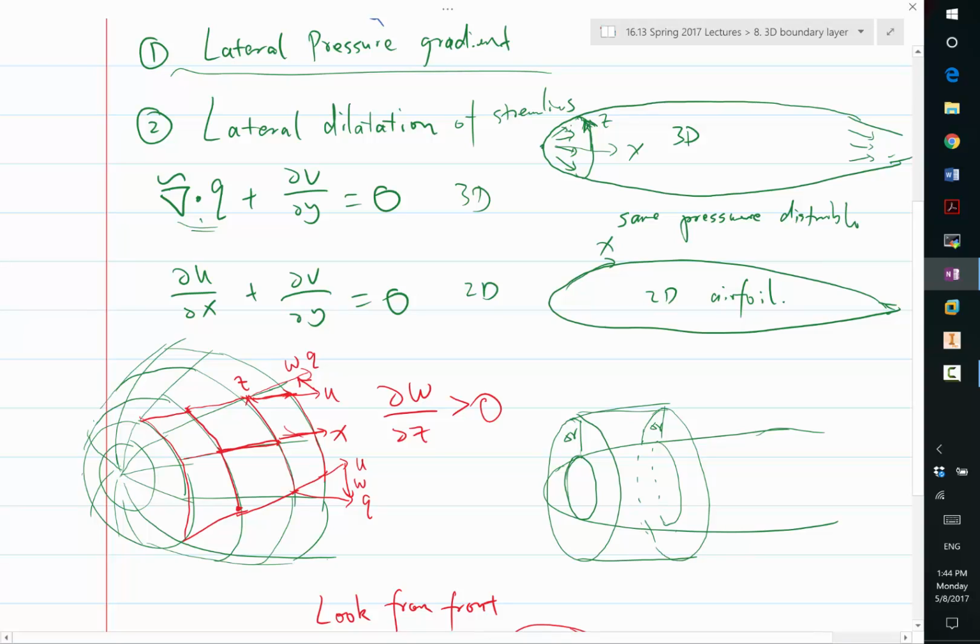So the y-directional velocity is going to be higher, and that tends to thicken the boundary layer by advecting the slower velocity from inside the boundary layer to outside. While if you have diverging velocities, that has the same effect as sucking flow from the boundary layer. So the velocity tends to go more downwards, and that slows the growth of the boundary layer.